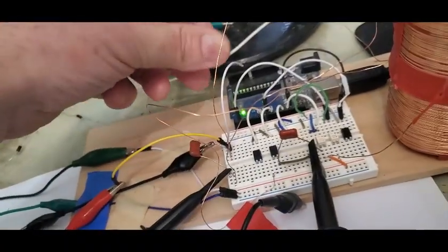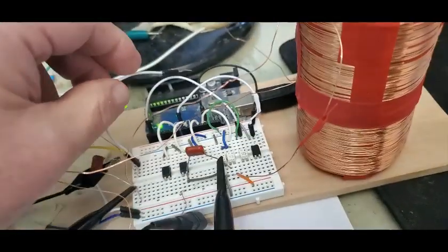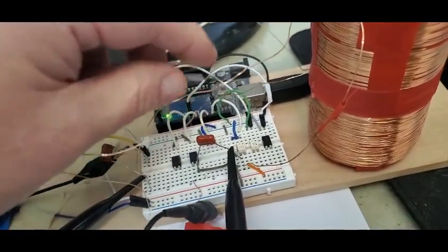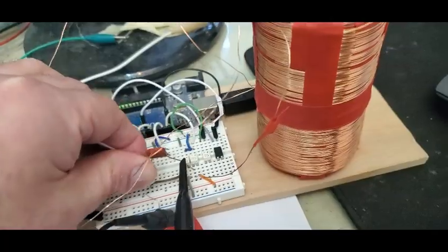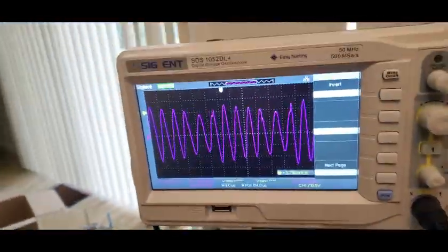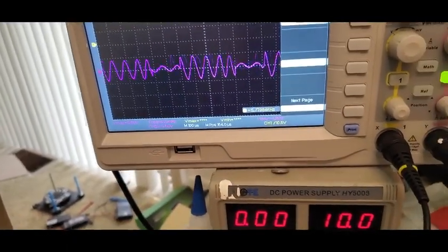And so if we just connect a line from this ground to where the negative probe of our oscilloscope was, that's kind of bent, but it's good enough. You see, it goes back to being all funky. So now we'll take that out and put it back in.